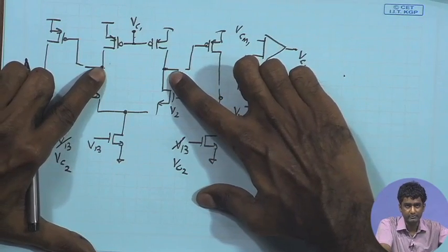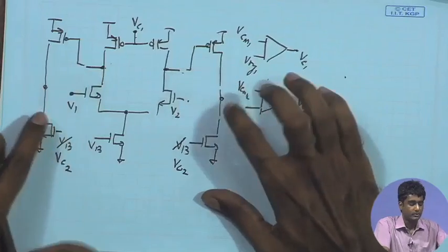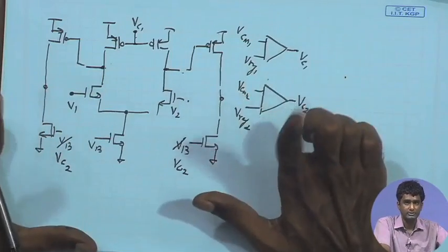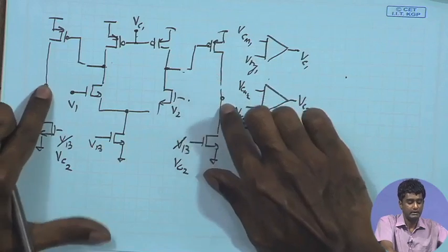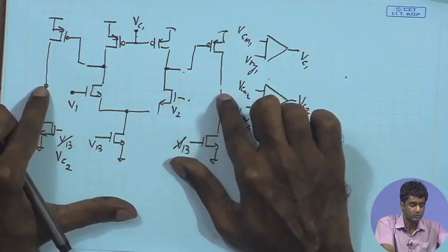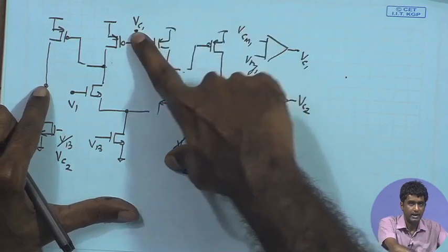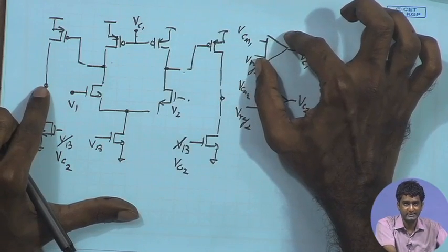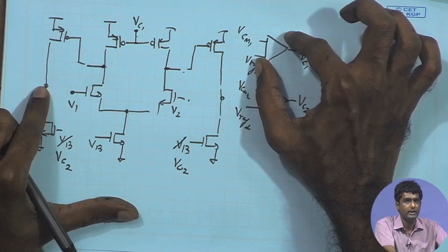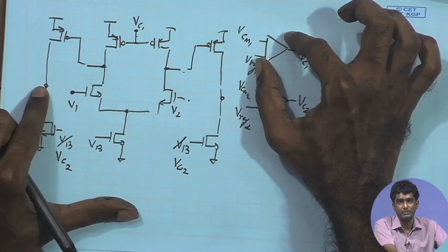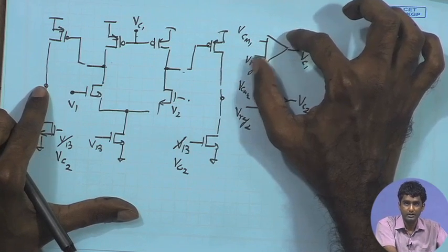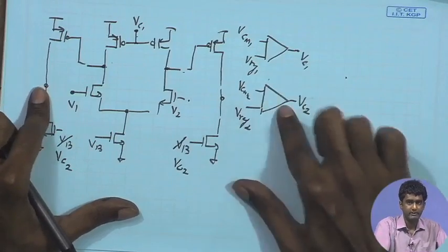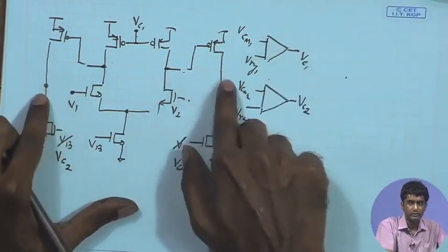So, in that case, I can control the two DC bias points for the output stage and the first stage separately and safely. In simulation exercises, we can see what happens if we rely on a single error amplifier and try to control the output DC point by just adjusting the VC1. That can be a more risky case, and it will be more clear when we look at the corresponding simulation example. It will be better to explain with that. So, in general, for more robust design, people prefer having separate common mode feedback for the two stages.